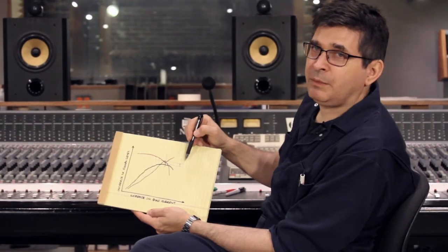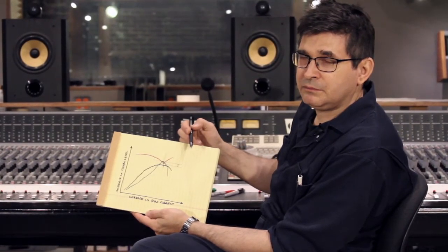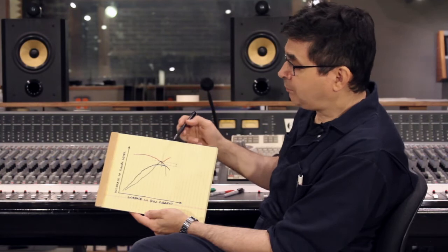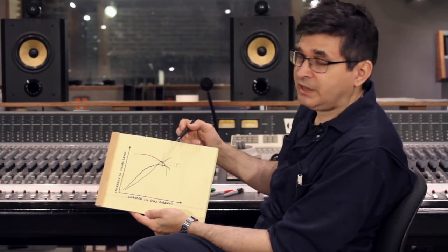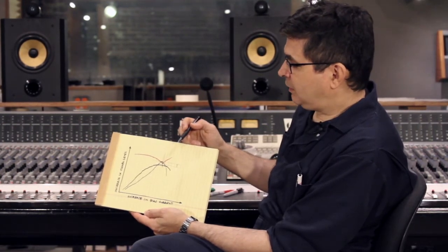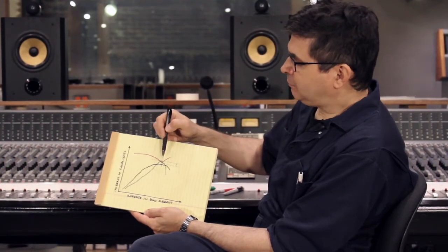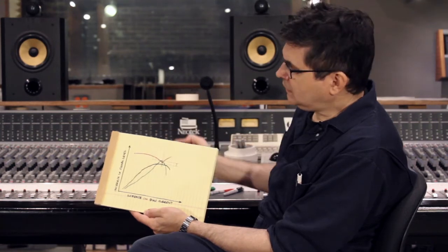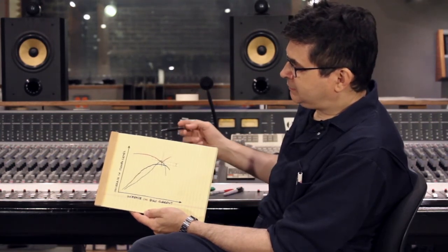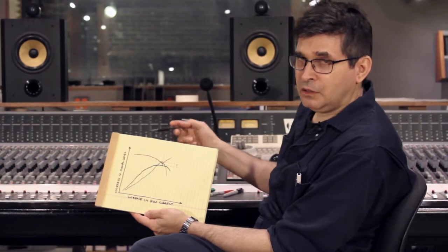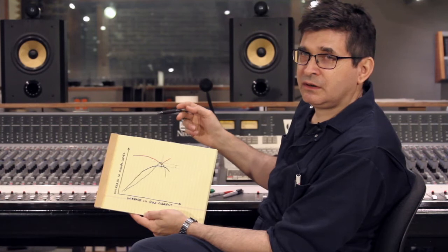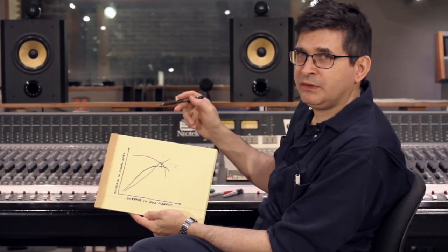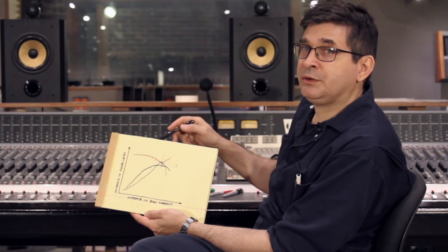These figures, the overbias figures for every tape and every head manufacturer, are published, and you can refer to those published tables. Most of them are available on the internet. But it is also possible to find that critical bias point by ear. And the way you would do that is by setting the machine up to record a low frequency tone. And I say low frequency because with low frequencies it's easy to differentiate between the noise and distortion components and the signal when you're listening to a low frequency tone.